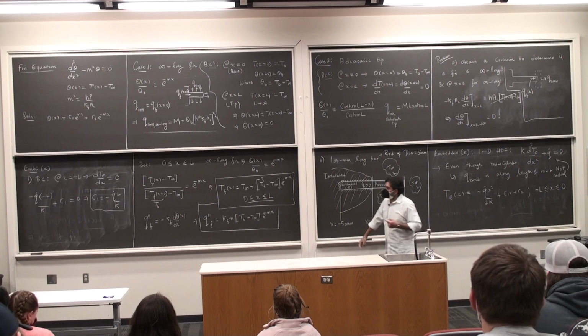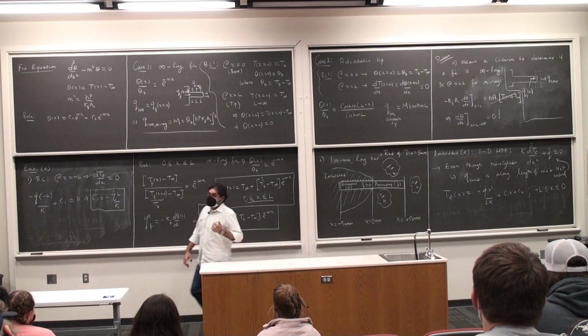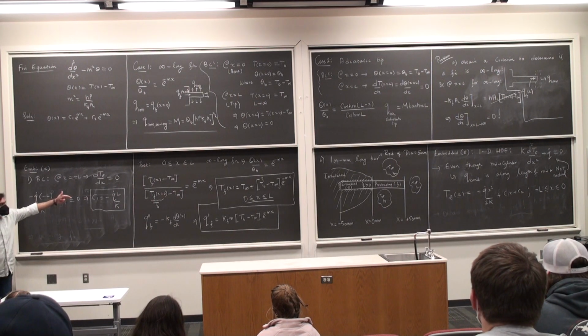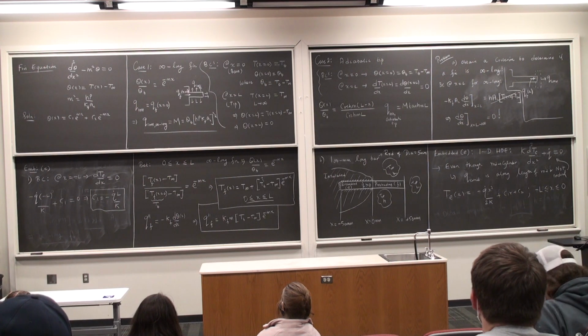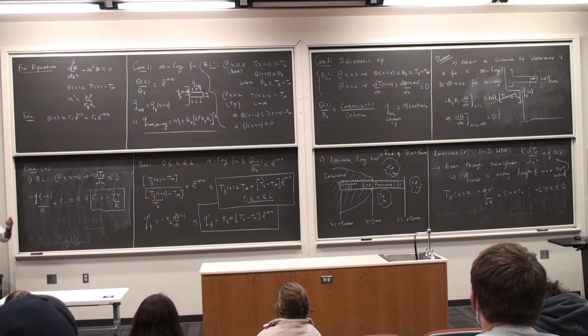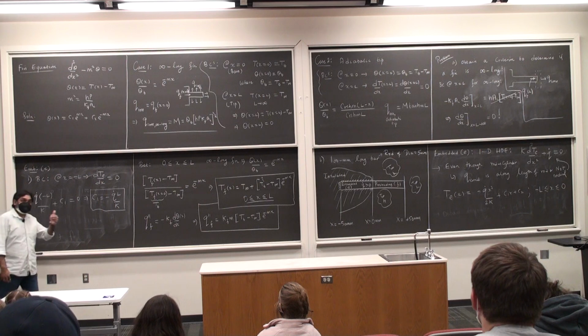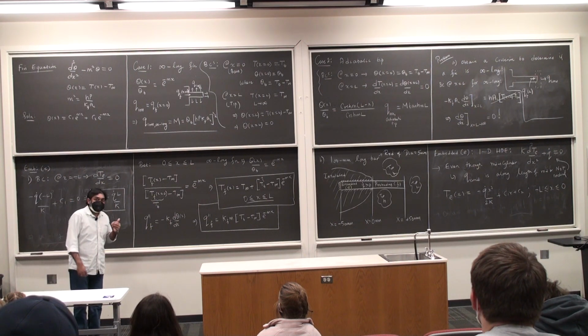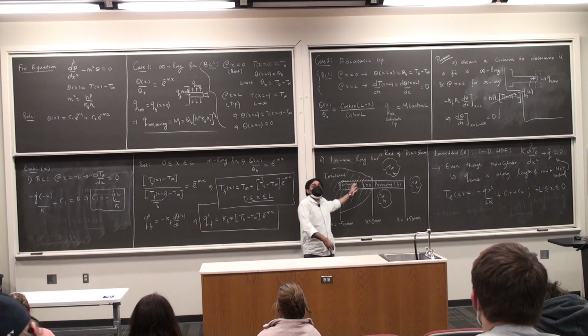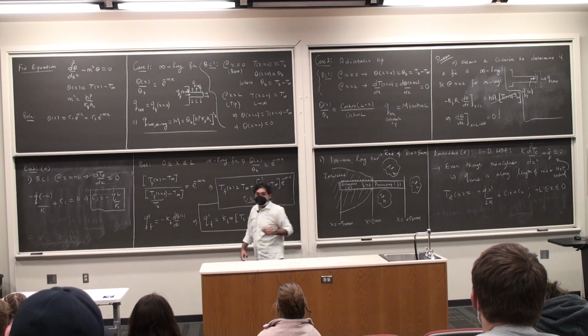Okay? And so not necessarily a continuity in the slopes, because the temperature profiles are completely different. For a fin it's an exponential profile, this is a quadratic, so there is going to be a slope discontinuity for the temperature even though they are made of the same material. In one of your homeworks you had a wall with different materials and you saw that there was a slope discontinuity. In this case, even though there is the same material, their behavior is of two different creatures, so they are not going to gel well with each other. Okay?